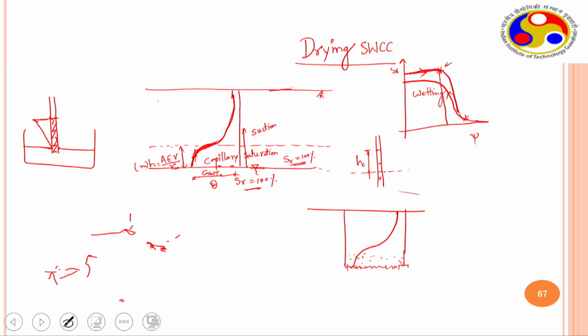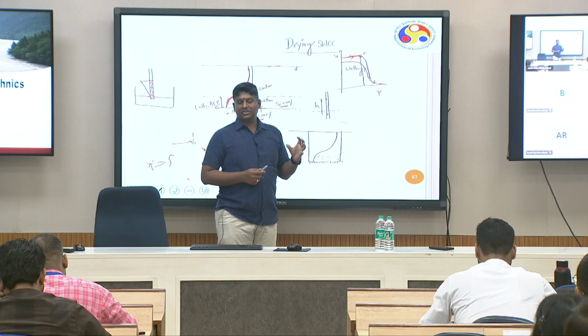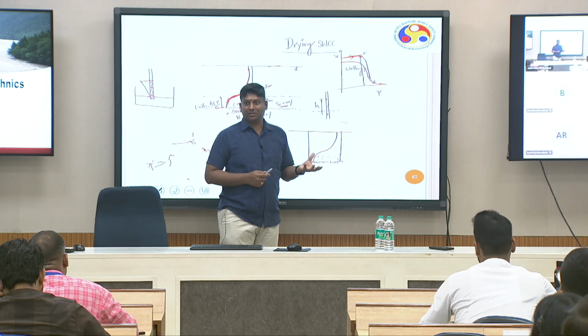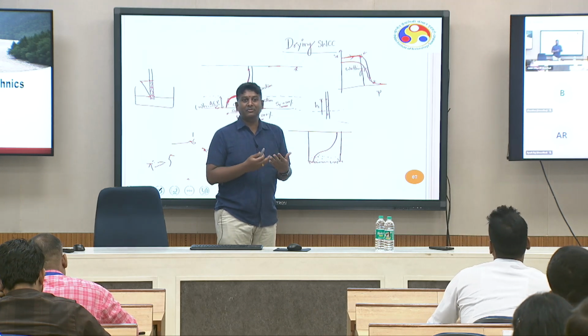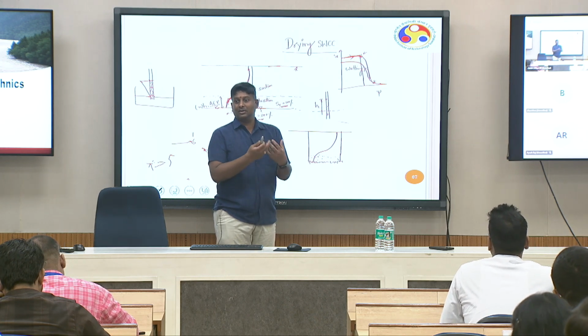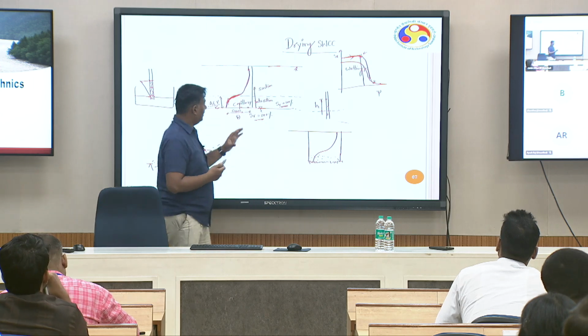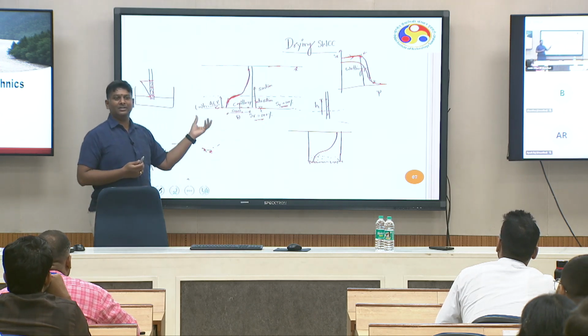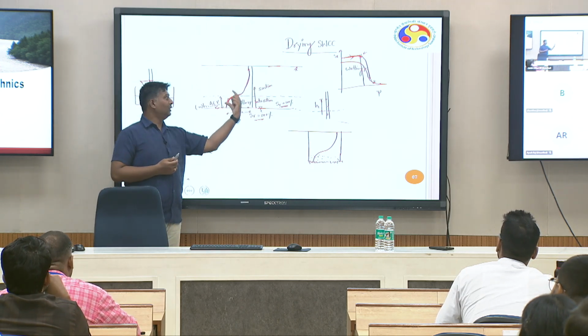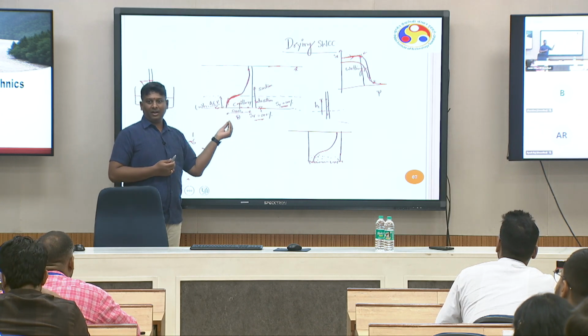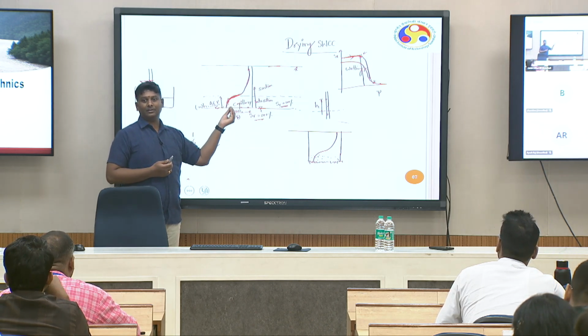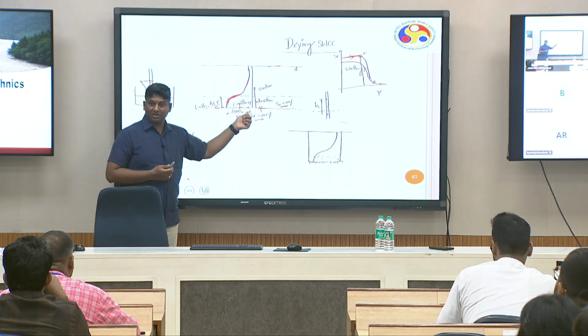So this is what I was describing, and in the previous case I was describing a drying phenomenon, right? There's a drying phenomenon that is taking place where I was trying to suck the water from the initially saturated conditions. But here, although a similar concept was described, initially the soil was dry and it got wet because of the capillary rise here. So this is a wetting phenomenon that is being described.